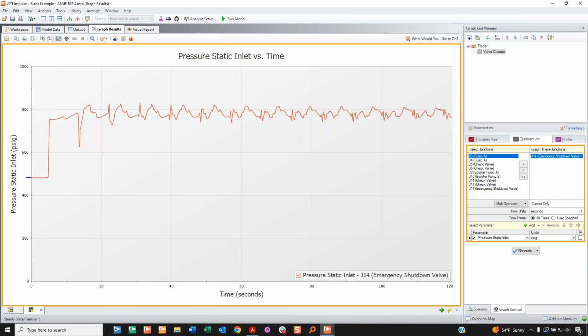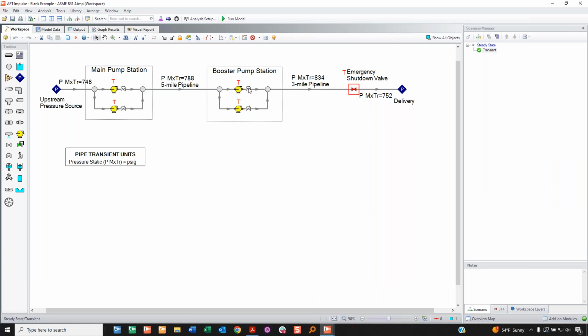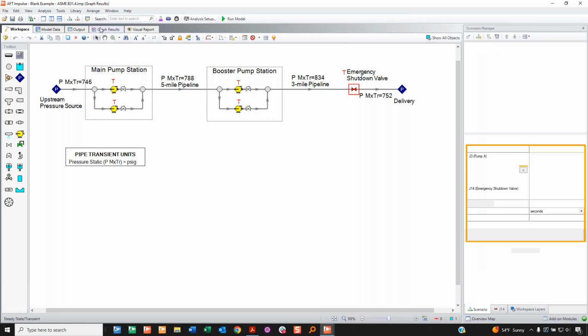Well, for the first little while, it's steady, because as the valve is closing, it turns out it's actually not controlling flow much, but it's around the delivery pressure up to the other downstream side, maybe about 480 pounds or so. And then it skyrockets from the valve being closed. So remember, kinetic energy converting to potential. We're seeing this pressure rise, and then that will cause flow to stop. And then there's a bunch going on with the waterhammer cycle, where waves are reflecting off each other, or waves are reflecting off components. We have the check valve, which ends up closing, so it kind of locks in a pressure wave here.